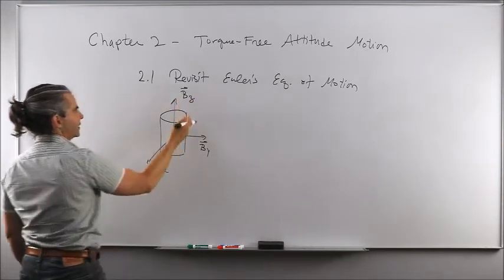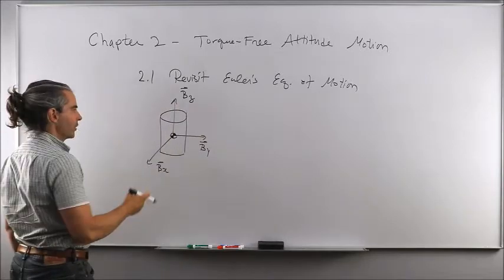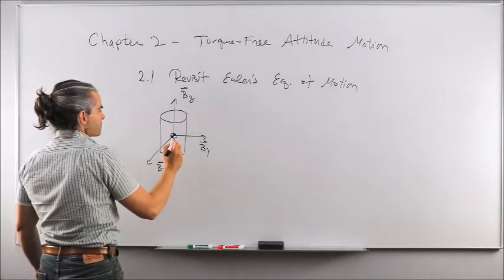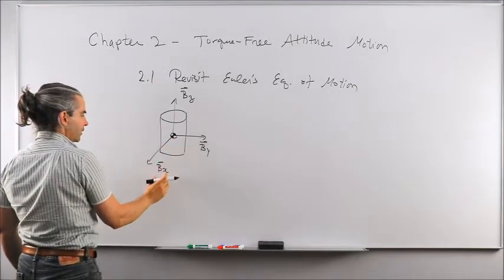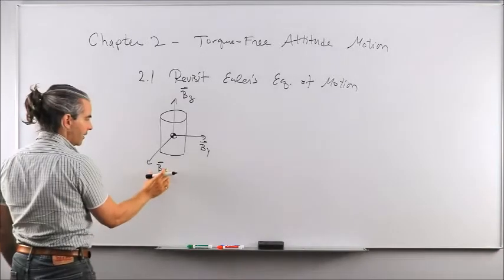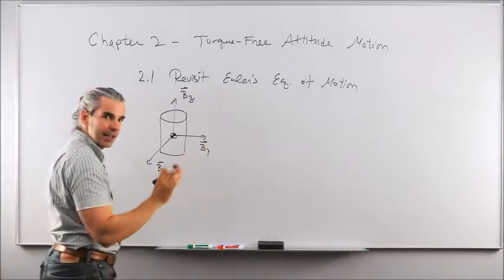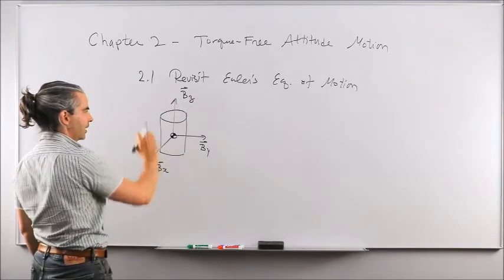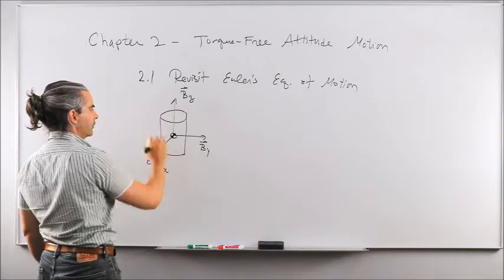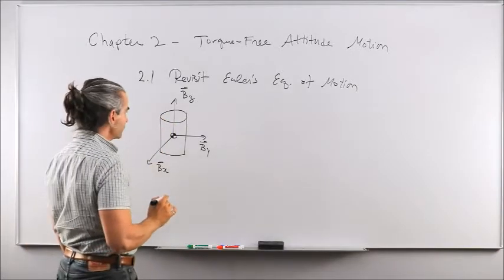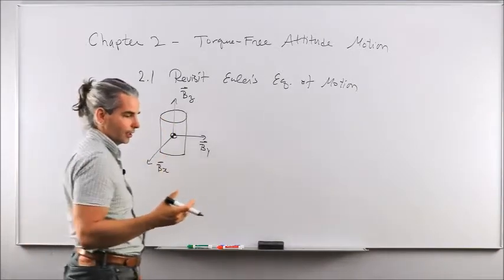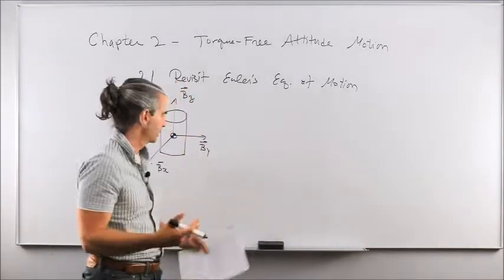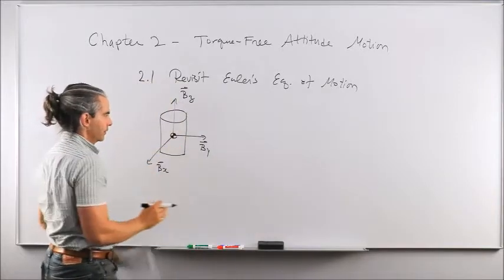And we're going to set the z direction of the body fixed reference frame towards this axis of symmetry, such that we end up with the principal moments of inertia about Bx and about By to be exactly equal to each other, and that one to be different, just because of the sheer geometry of the rigid body considered here. Now, this is obviously assuming a mass distribution which is constant throughout the body, okay?